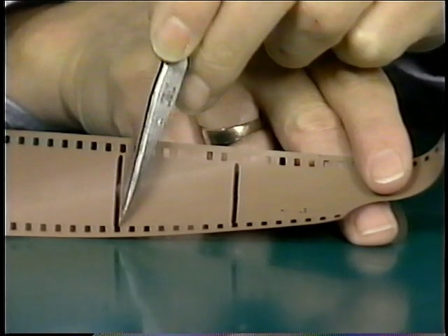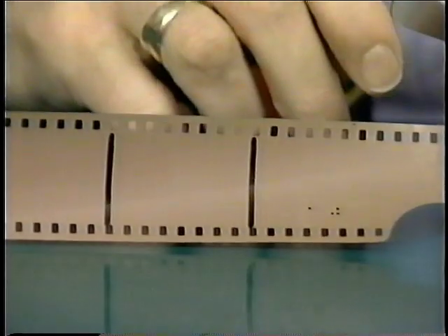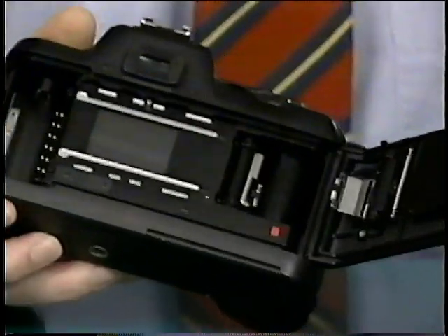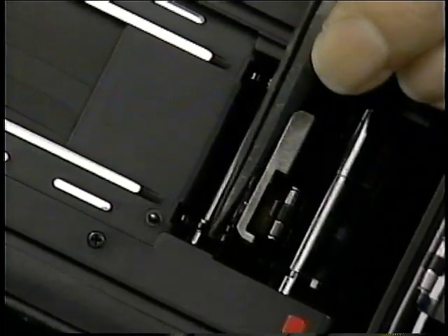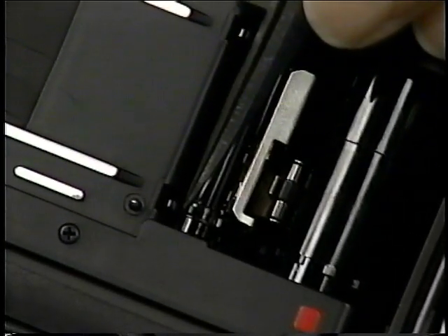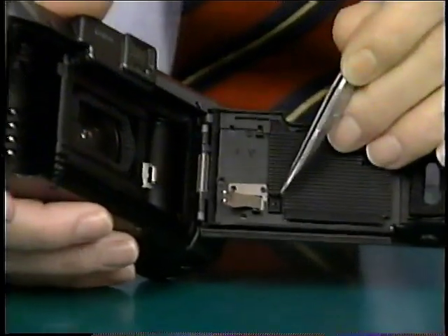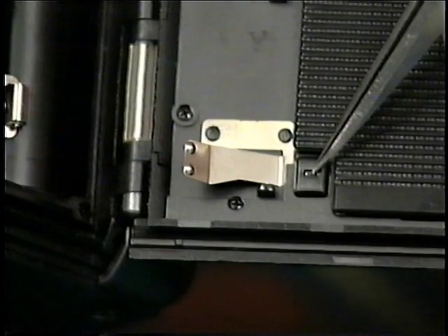But do remember this, there are exactly 8 perforations from one frame to the next, and that's how film is metered. Cameras meter film or count frames two different ways. One is mechanical, and that is using a sprocket which counts off literally 8 perforations on the 35 millimeter film. This is a sprocket in a typical 35 millimeter camera. Some of the newer electronic cameras use photodetectors to do exactly the same thing. This is a compact camera, and you'll see this device here with 2 little windows in it.